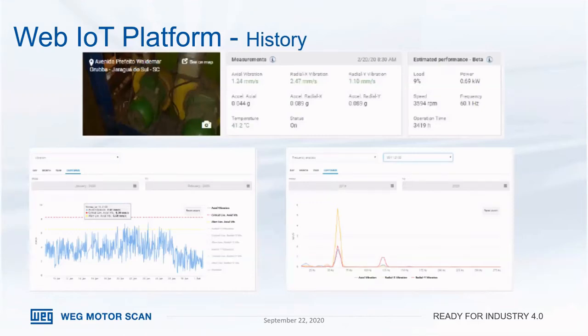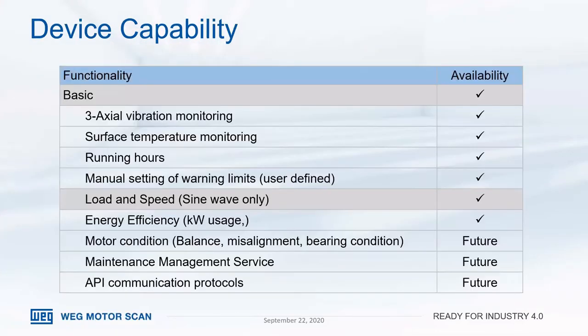And there's a couple more screenshots. Again, the vibrations, the temperature of the skin of the motor is listed here. And again, at the end of the day, it's not really to extrapolate all of this data and just look at it. It's really so the maintenance personnel can look at this and say, hey, we need to grease the bearings in the motor, or is there something outside of the motor within the environment causing an issue? Whether it's an environmental issue.